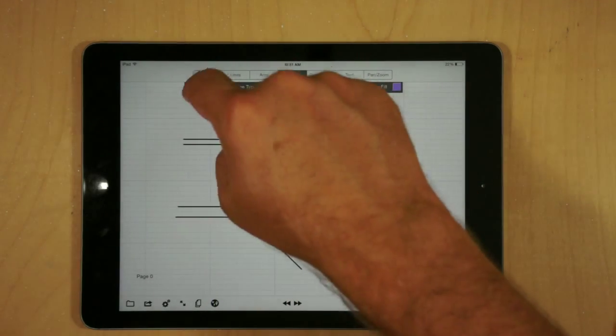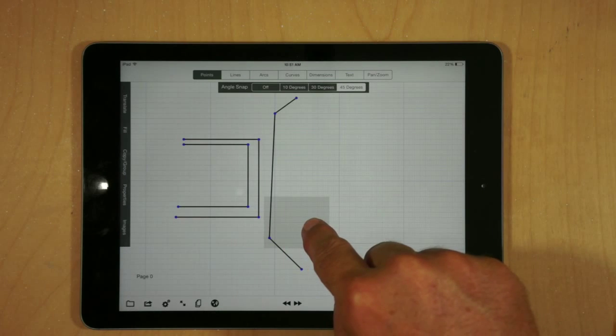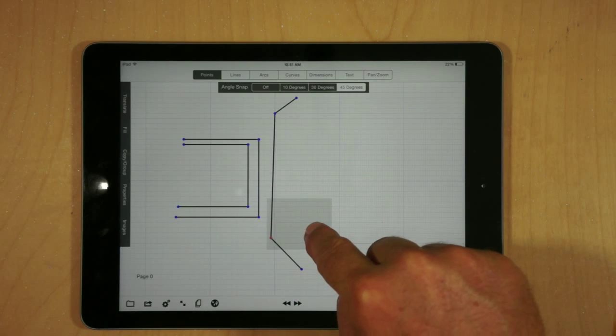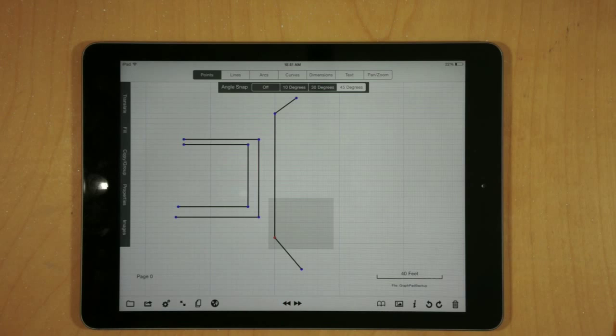Now there are disadvantages to this. One is that it's not particularly accurate, and so if you're trying to draw an accurate dimensional drawing, this is not useful. But in addition, it's unstable. So if you do a large drawing, at some point the algorithm breaks down and you'll get some corruption in there. So I try and recommend not using this feature very much.